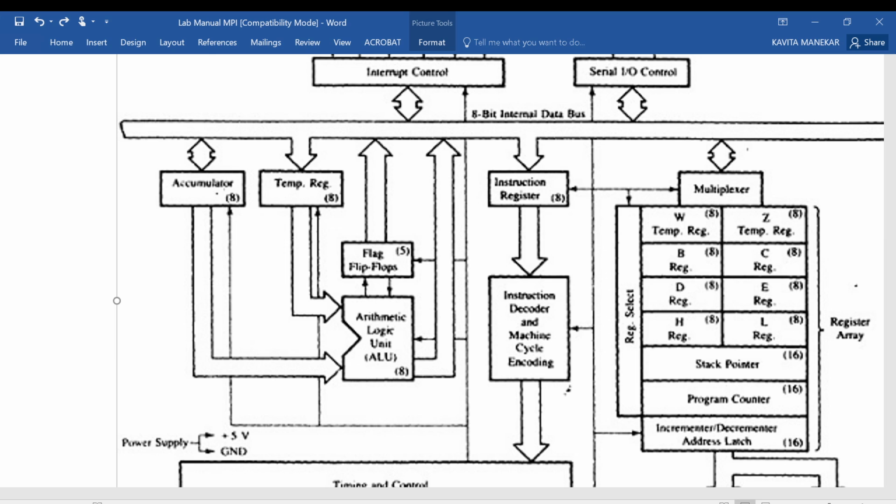Whether a carry is generated after 8-bit addition is indicated by the carry flag. And the auxiliary carry flag is used whenever an intermediate carry is generated after the lower 4 bits. The auxiliary carry flag is used by the ALU only. No one can alter the data of AC, that is the auxiliary carry flag. The remaining 4 flags can be used by the user.